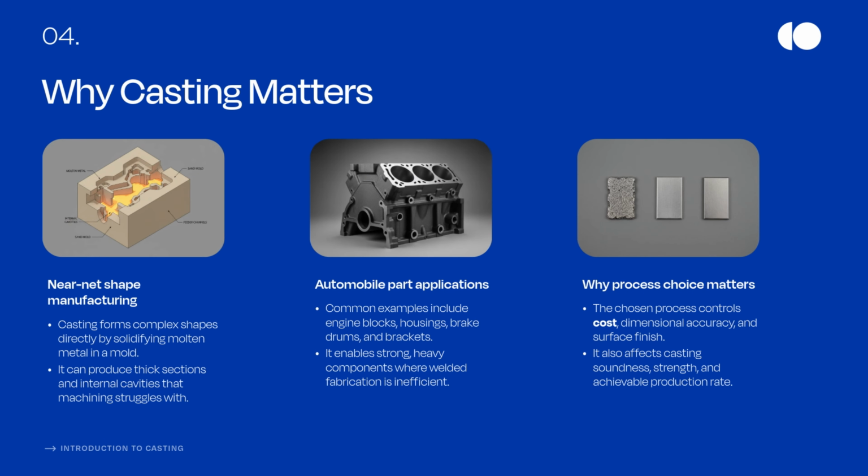Here, let us understand the importance of casting process. It's a near net shape manufacturing. Casting forms complex shapes directly by solidifying molten metal in a mold. It can produce thick sections and internal cavities that machining struggles with.